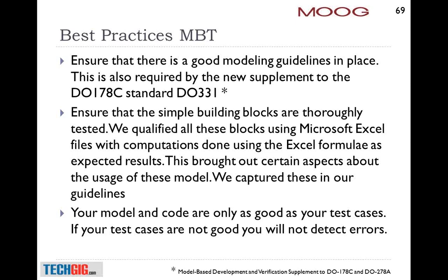The new standard has the DO-331, the model-based supplement. It has brought out certain rules and regulations on the model. It says that you should have good modeling guidelines. So if you are going to practice model-based testing, make sure that you have a very good modeling guideline so that your models are good. You have to ensure that all your system blocks, the subsystem level or the smallest blocks, are tested thoroughly. So make sure that you test them very thoroughly, and for our